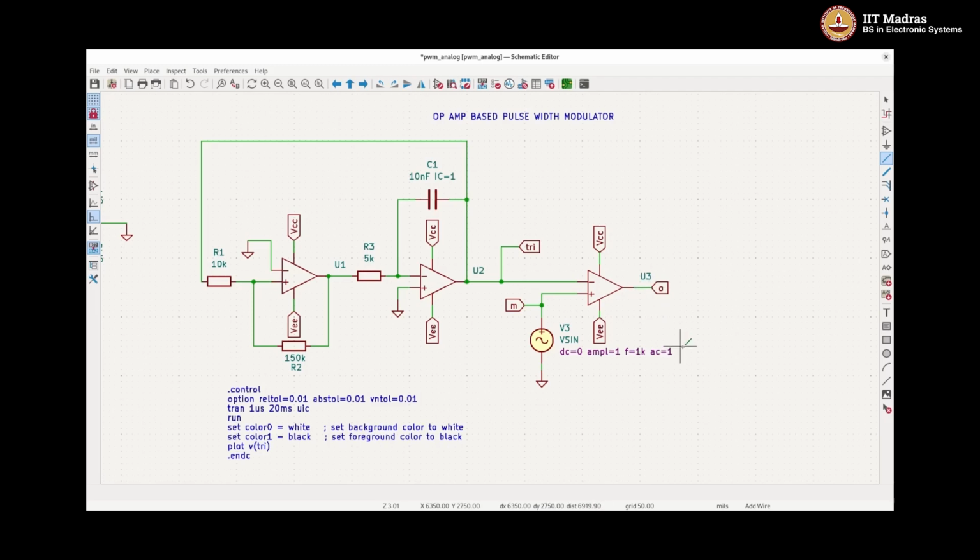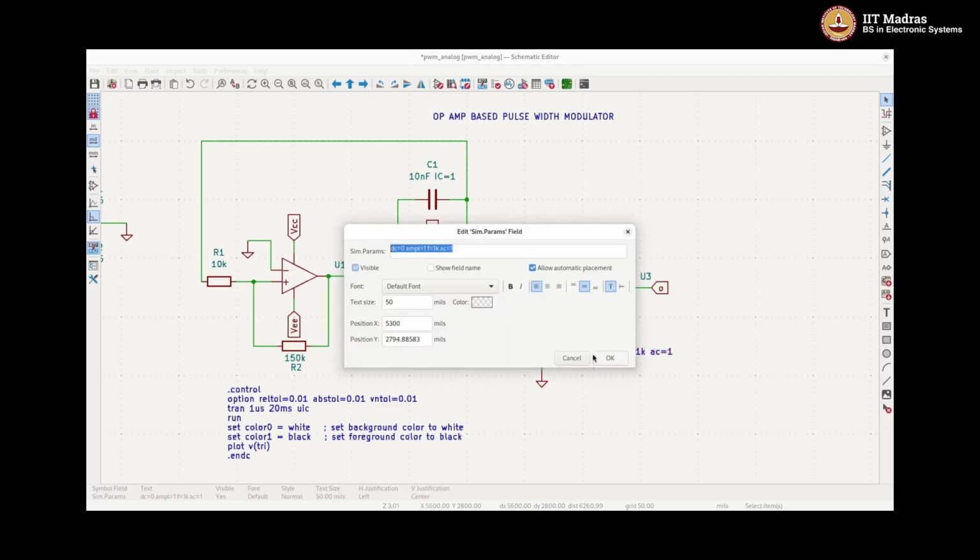So we can observe these waveforms. Now for the modulating signal, because I am expecting the triangle to be up to 1 volt peak, I will make the modulating signal go up to 80% of it, 0.8. And you see that the triangle was having around 57 kilohertz frequency we calculated.